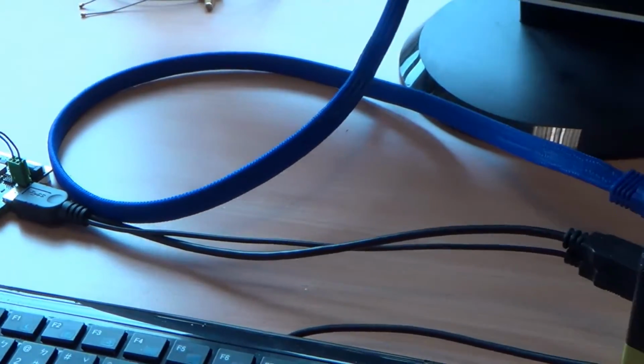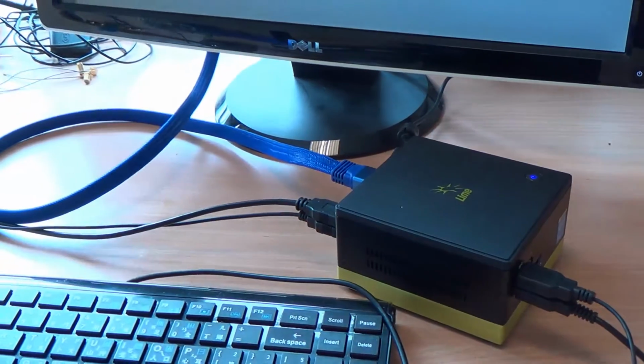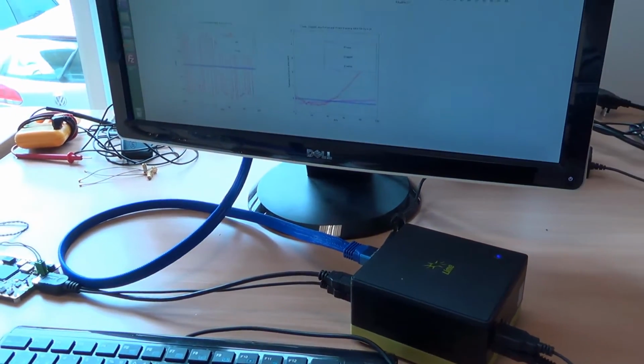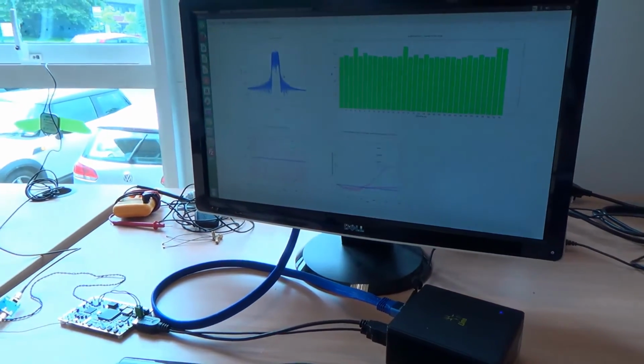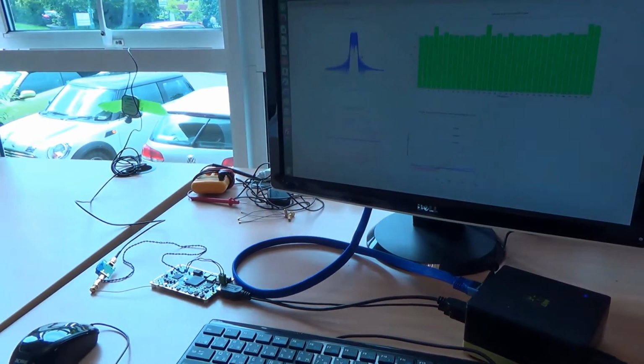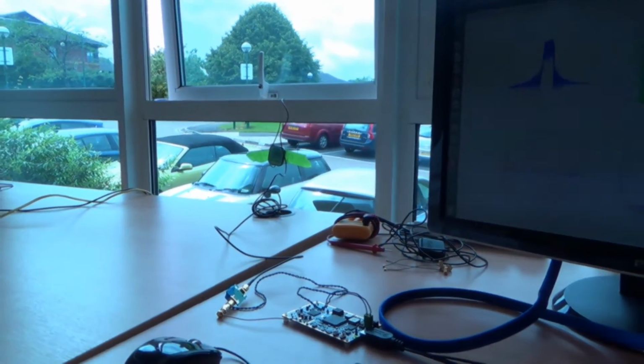Precision GNSS receivers benefit from the programmable bandwidth and high ADC rates available with the LimeSDR. The LimeSDR is configured as a low IF receiver using the internal numerically controlled oscillator to down-convert the signal to baseband, and then decimating the signal to reduce the amount of data that has to be processed in Octave.